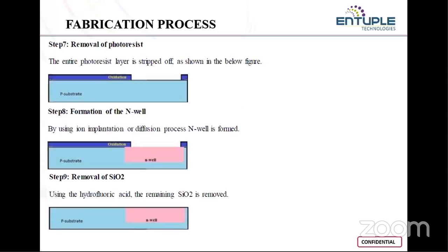It should be only for a fixed region of space. That is why we make use of protective layers like oxide, photoresist, etc., in order to avoid spreading of that diffusion material to the rest of the p substrate material.